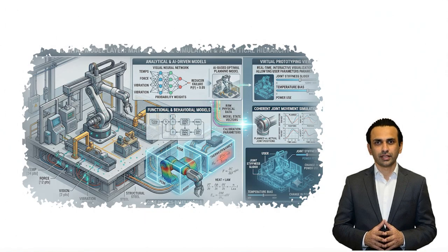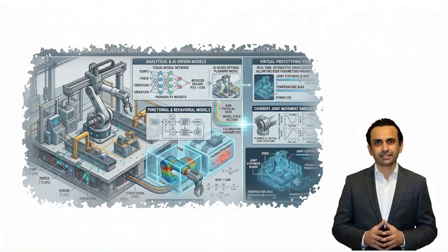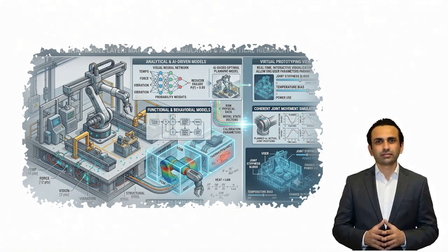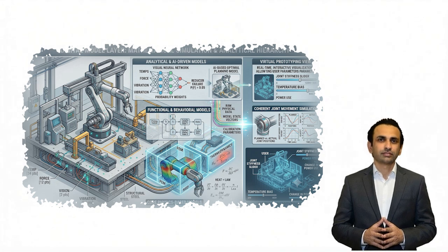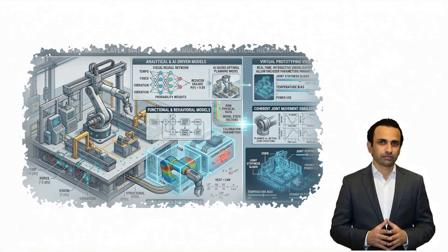Layer 5, Digital Model layer. Now we reach the heart of the digital twin, the digital model layer. This layer represents how the asset works. It may include physics-based models, behavioral models, rule-based logic, statistical representations. Examples: thermodynamic models for HVAC, stress models for turbines, flow models for pipelines. This is what differentiates a dashboard from a true digital twin. The model understands cause and effect, dependencies, system behavior. Change an input here and you can simulate outcomes before they happen.